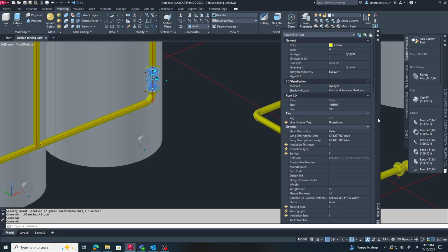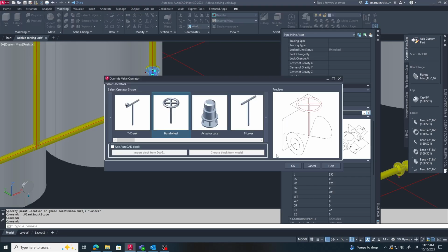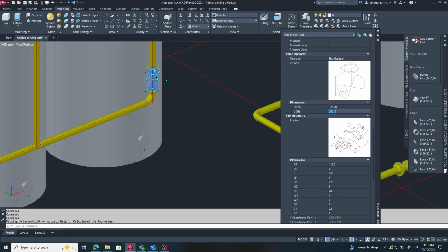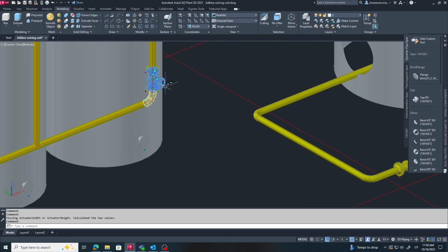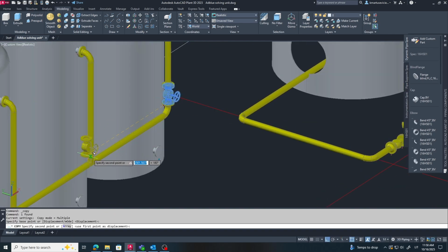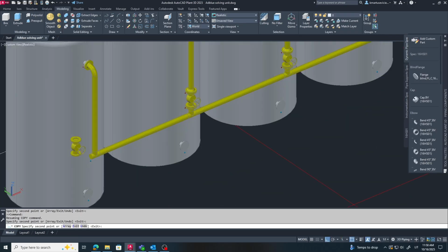Now it's time for some more copy work. Let's add valves to each inlet line leading to the vessels. The principle is simple. All nozzles remain closed by default. When you want to fill a specific vessel, you open only that nozzle. This can be done manually, where personnel open it by hand, or automatically, with the operator controlling it from the computer in the control cabin. Once the valve is open, the filling process begins.